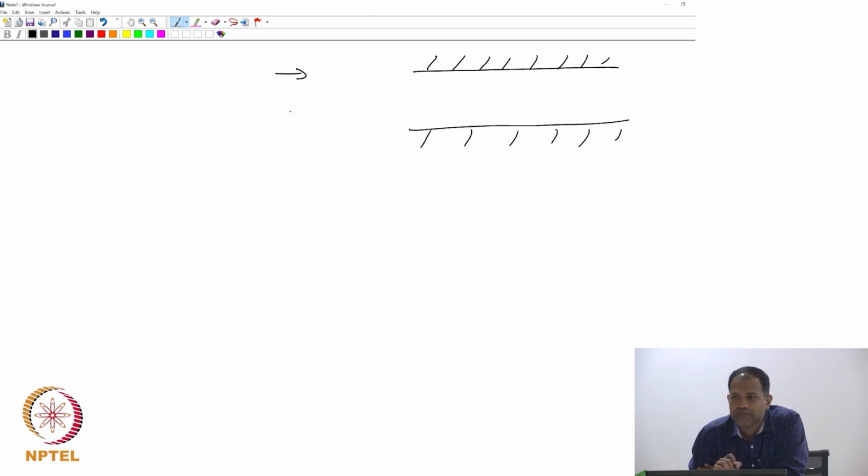So when I say the velocity profile is uniform, velocity is a vector, so it has a magnitude and a direction, and neither of them is changing in space. So there is a fluid coming from the left with a constant velocity. The typical way to draw it is two parallel lines with nothing changing in between, approaching the plate.